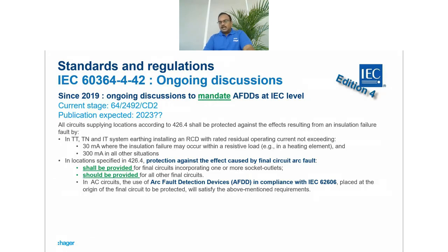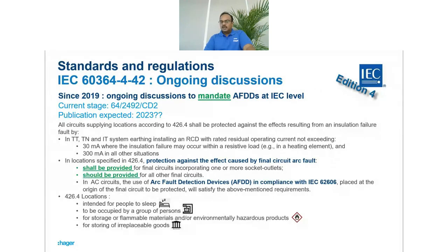In this, some locations have been modified a little, but it's okay. They have not mandated it for every place. They only said that if there is a place intended for sleep, it has to be used. If it's occupied by a group of persons, we need to use it. Inflammable places, irreplaceable goods, wherever they are, it should be used. Where agricultural livestock are kept. These kinds of places and circuits need to be mandatorily used with AFDD. This is edition 4.